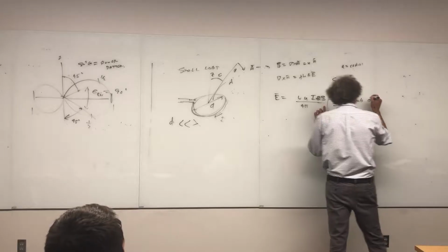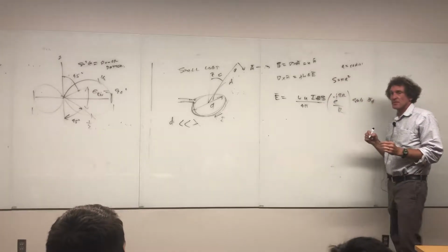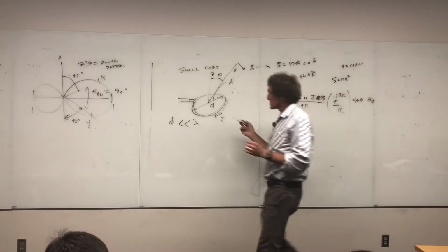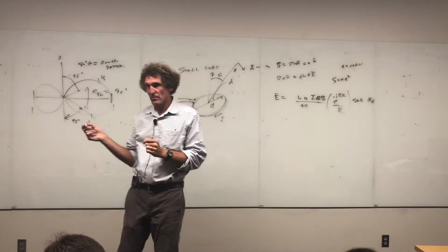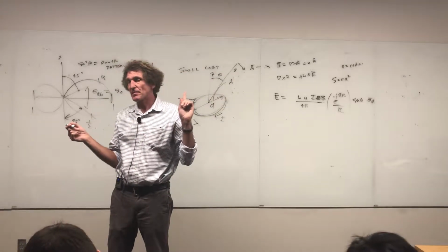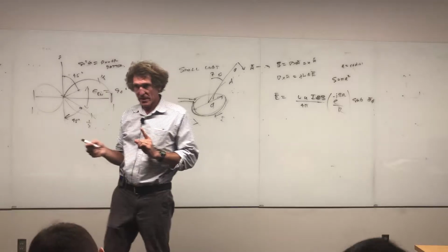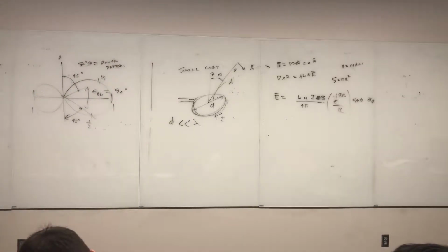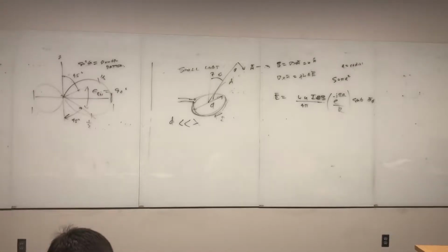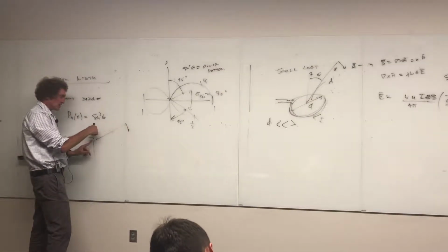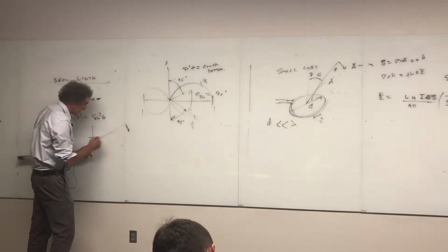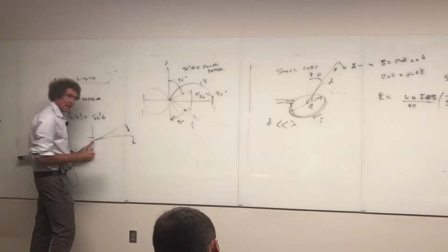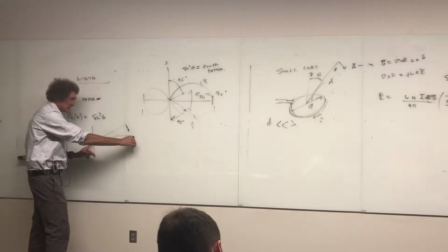phi direction. Now take note that the E field's in the phi direction, and this is something I didn't state quite right yet. Here's something you always remember about wire antennas. If you have a straight wire antenna like this, regardless of whatever you want to call this direction, x, y, z, the E field will always have a component that projects onto this thing. For instance, if you look at the E field at this distance, it's straight that way, right? It's in line.